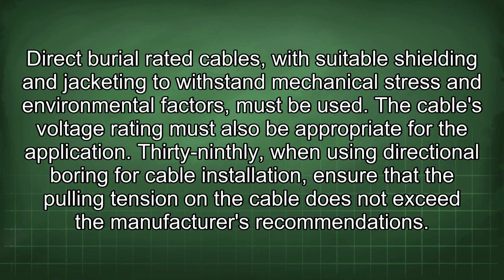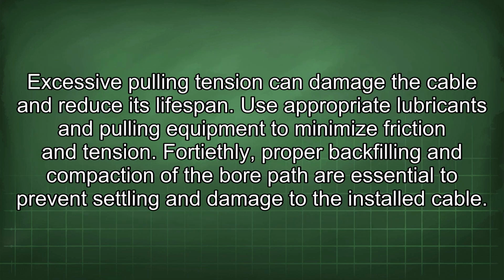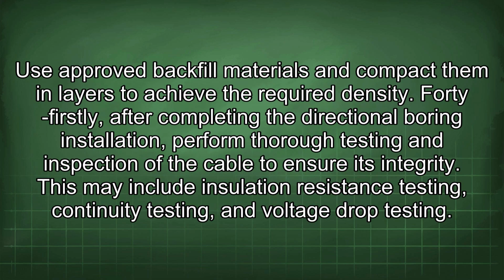39thly, when using directional boring for cable installation, ensure that the pulling tension on the cable does not exceed the manufacturer's recommendations. Excessive pulling tension can damage the cable and reduce its lifespan. Use appropriate lubricants and pulling equipment to minimize friction and tension. 40thly, proper backfilling and compaction of the bore path are essential to prevent settling and damage to the installed cable. Use approved backfill materials and compact them in layers to achieve the required density.